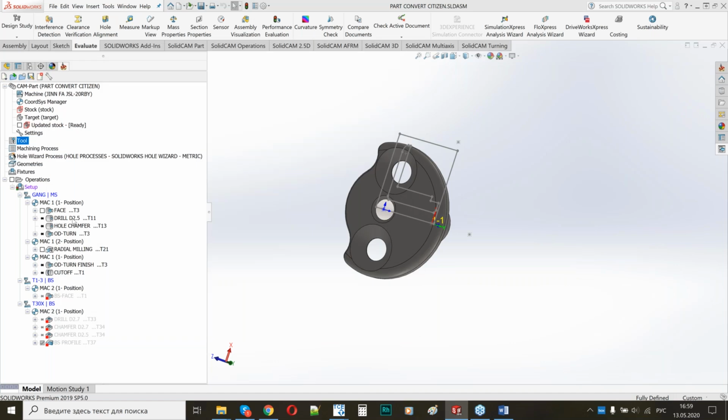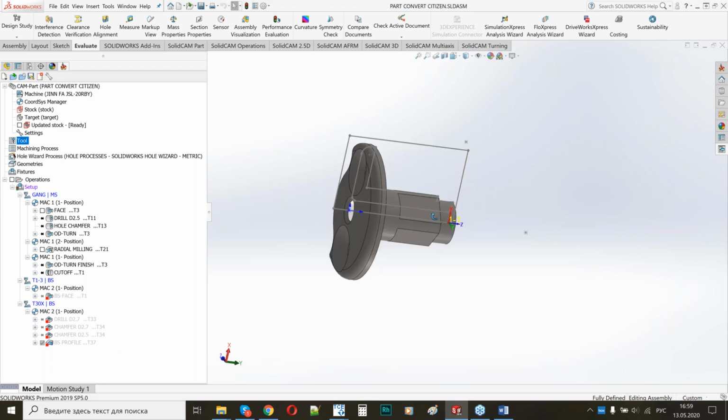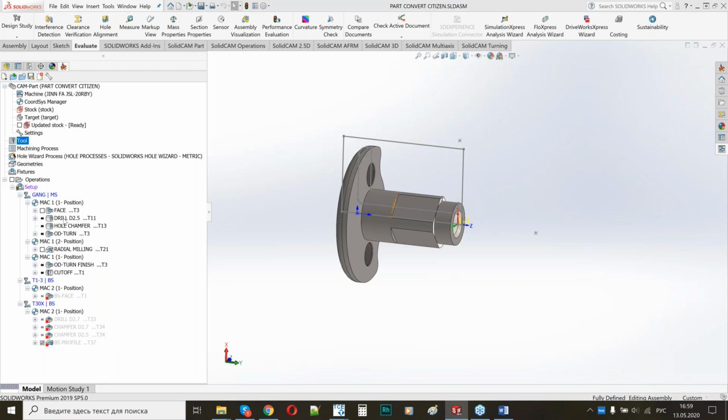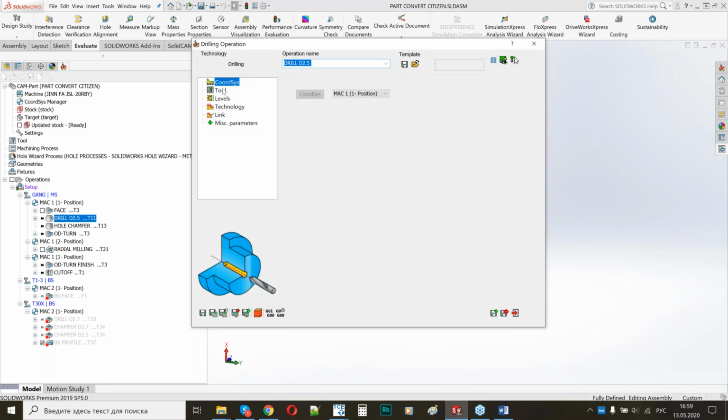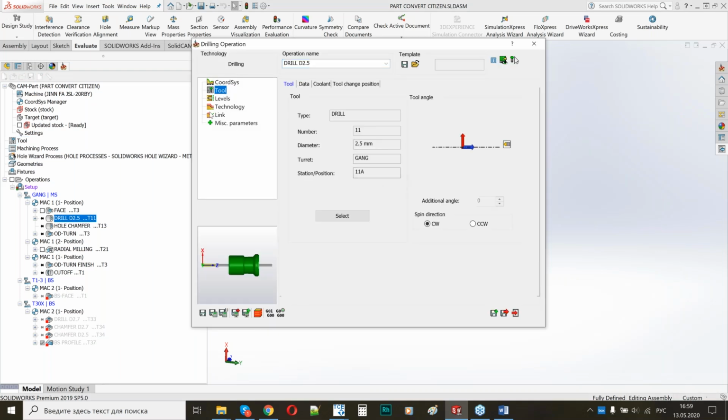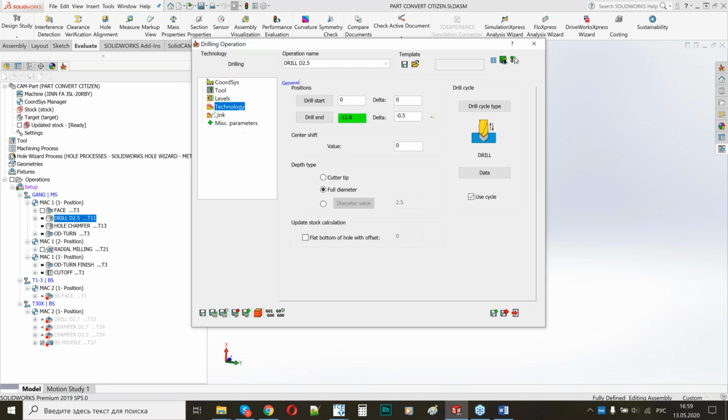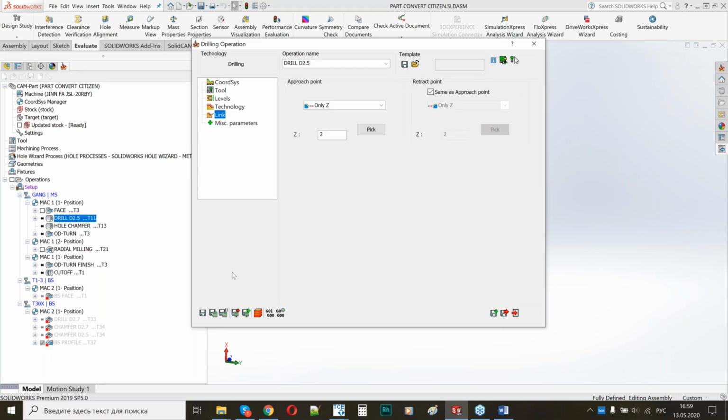The next step here is to check the lead in, lead out, and retract of the tool. The first tool is the drilling tool here. Because it was used on the back spindle, I need to check my retract. It's just Z2. In the previous project, Z2 meant that the back spindle would be retracted 2 mm out from the face of the main spindle.